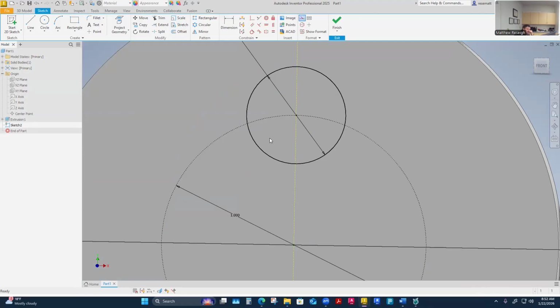I had to project that one, then I had to draw this one. And then I'm really not picking an intersection point. For the coincident constraint, I'm picking the center of the circle and then this, and then it will drive those together. That's because my circle's already first constrained to this, so it can only drive it down to that circle.